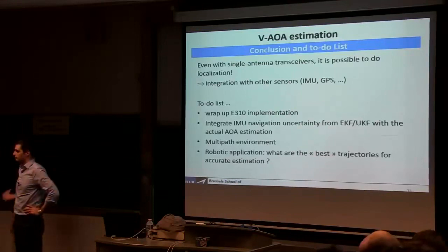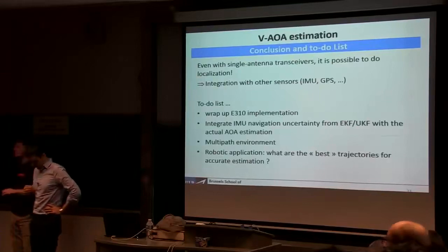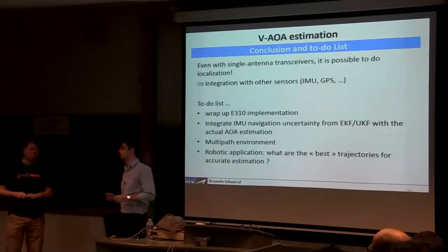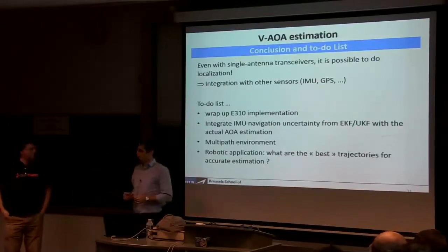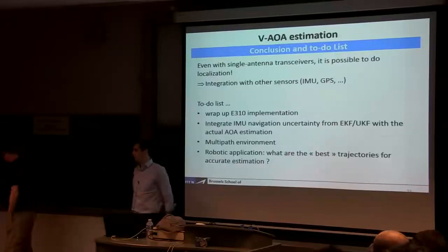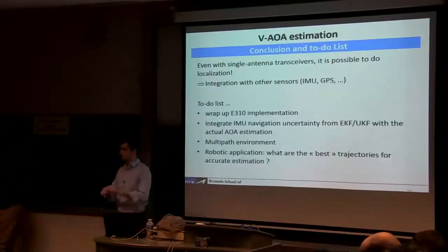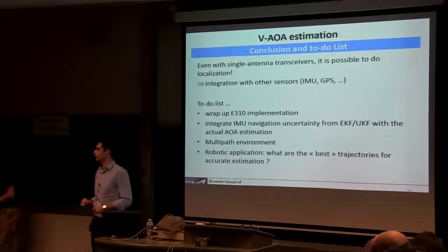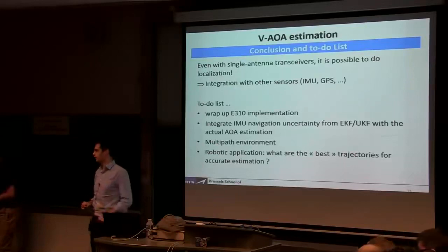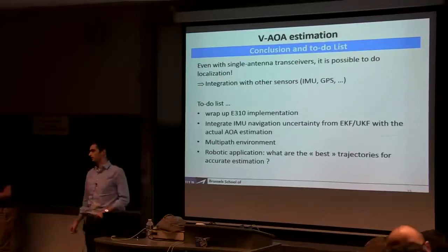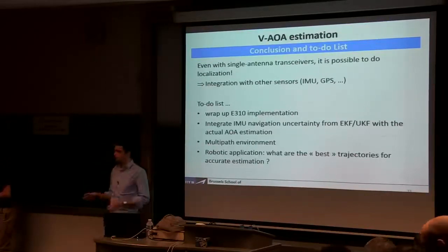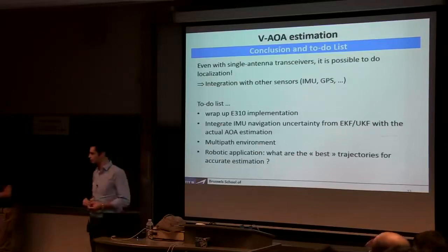Do any of these platforms you've worked on have a magnetometer? Because maybe you can get help for the orientation. Yeah, so the question is if there is a magnetometer on the IMU. Well, yes, there is. I've talked a lot with people from the control side over these things, and they all advise against using magnetometers because they're very sensitive to electric fields. If you have a computer running next to it, this is going to affect your magnetometer reading, and this might be critical in the long run. So yeah, in general, people don't use magnetometers that much.